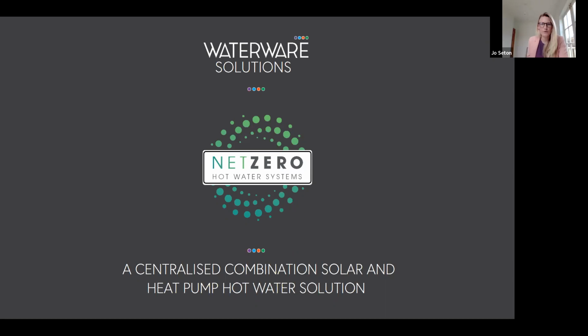Sure. So there's just one question from the audience, and I don't know whether you can speak to this one. It's more to do with a domestic situation. For a domestic home, integrating solar PV to a heat pump system, does one need a large battery to maximize savings? In a residential system, typically, yes. You don't get that same capital efficiency that you do with a centralized system, so it doesn't fit together quite as well. One of the issues you've got with solar PV for residential is your usage is out of phase. So your peak power requirements are at nighttime when the sun's not shining.